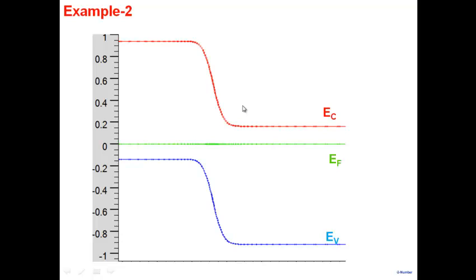All right. So we can know from here how much the built-in potential is. We know the direction of the electric field. We know it is in equilibrium. We know which one is P, which one is N. And once you sketch this, if I go into a region like this here, the electric field is 0. So what will the drift current be? Electric field is 0, so electron drift current is 0. Electron diffusion current, 0. Net current is 0, right? And the same happens here also.